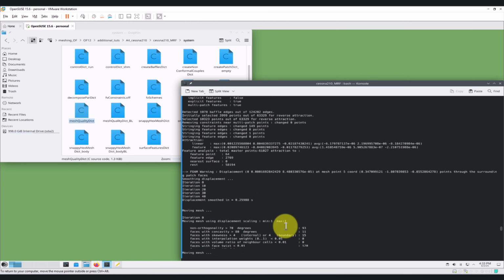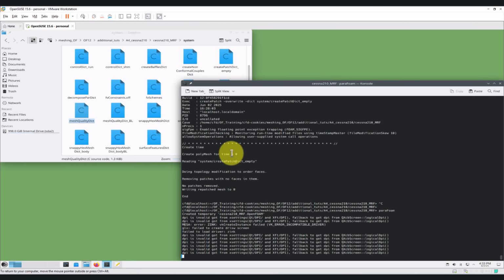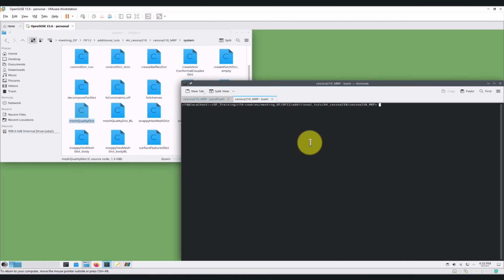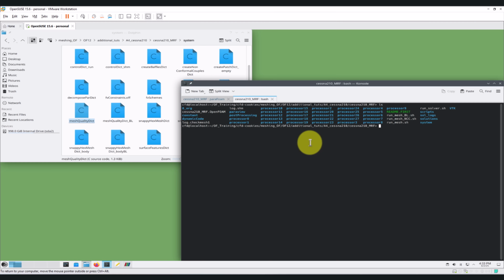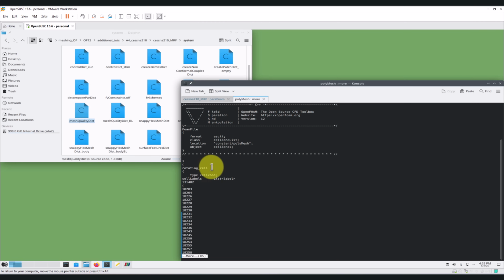So now that we have this, after this discussion let's visualize our mesh, because here, and actually let me open another tab, we have that cell region. Let me go and see the constant, see the polyMesh, and look at that. Here you're going to find faceZones and cellZones. So when you see this one, it means that you created that cellZone, you have it there. So more cellZones, and there you go, rotating cell, and this cellZone you can now access.